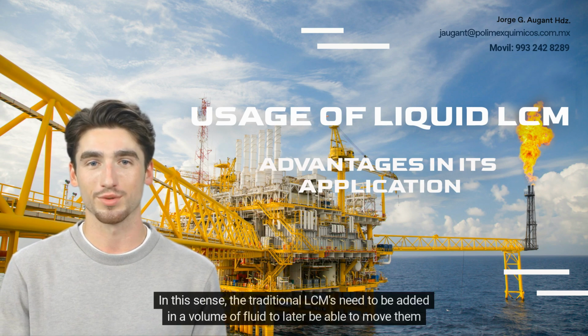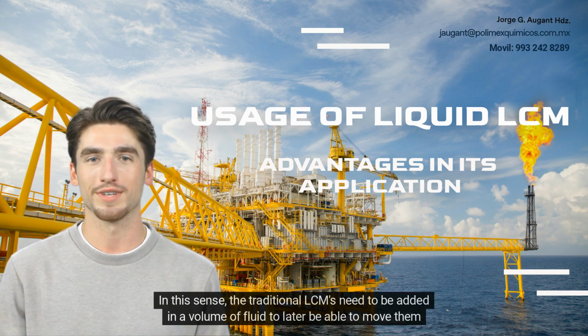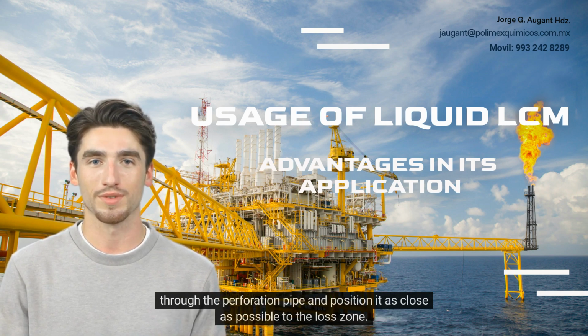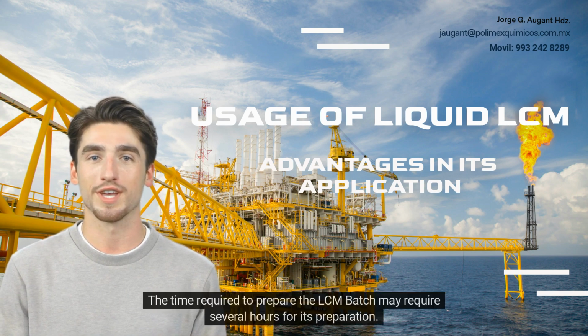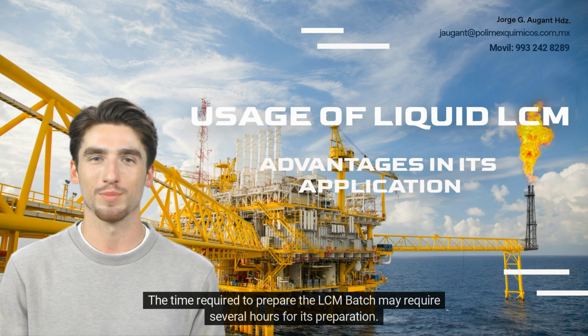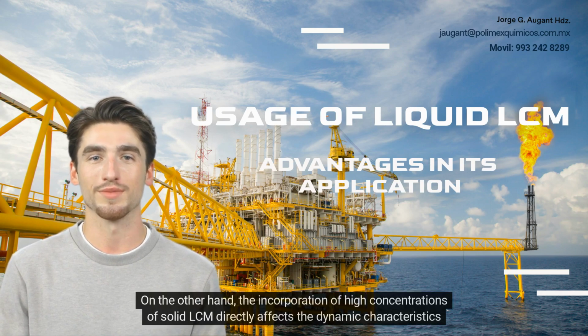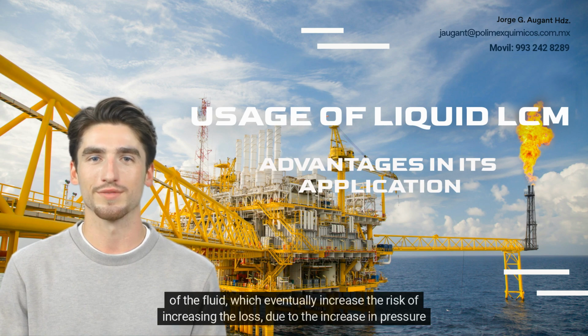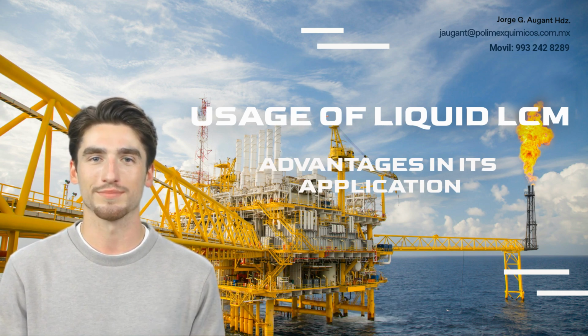In this sense, the traditional LCM needs to be added in a volume of fluid to later be able to move it through the drill pipe and position it as close as possible to the loss zone. The time required to prepare the LCM batch may require several hours. On the other hand, the incorporation of high concentrations of solid LCM directly affects the dynamic characteristics of the fluid, which eventually increases the risk of increasing the loss due to the increase in pressure in the annular space.